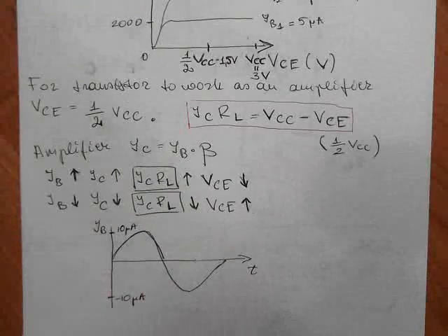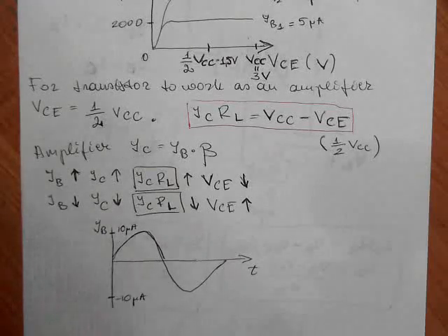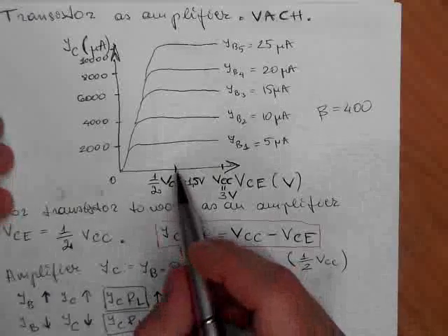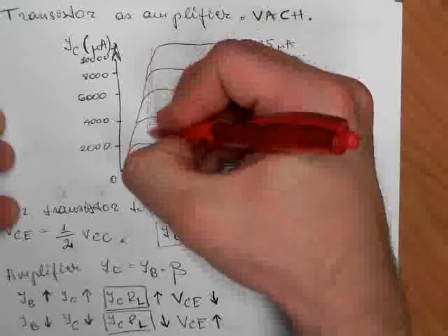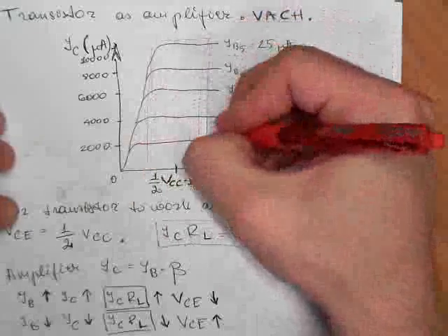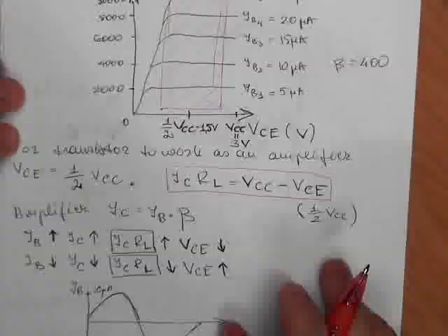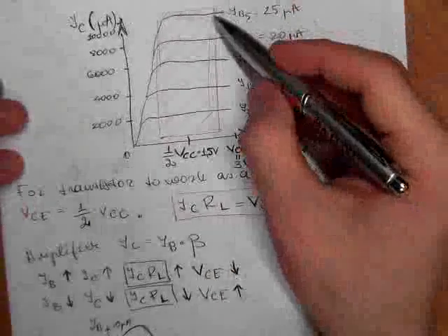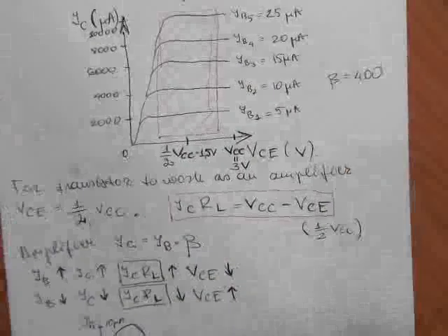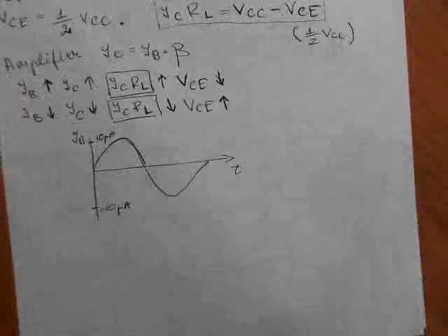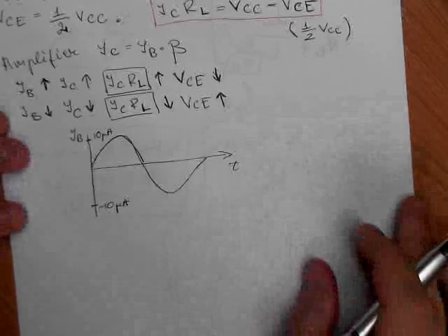Now, when we say this voltage, this voltage is always in the so-called linear region of the transistor. So it is like this region, the linear region. It means that these curves are equally distributed. As you can see, they are nicely equally distributed, these black curves. So this linear region is represented by this equation: IC is beta times IB.